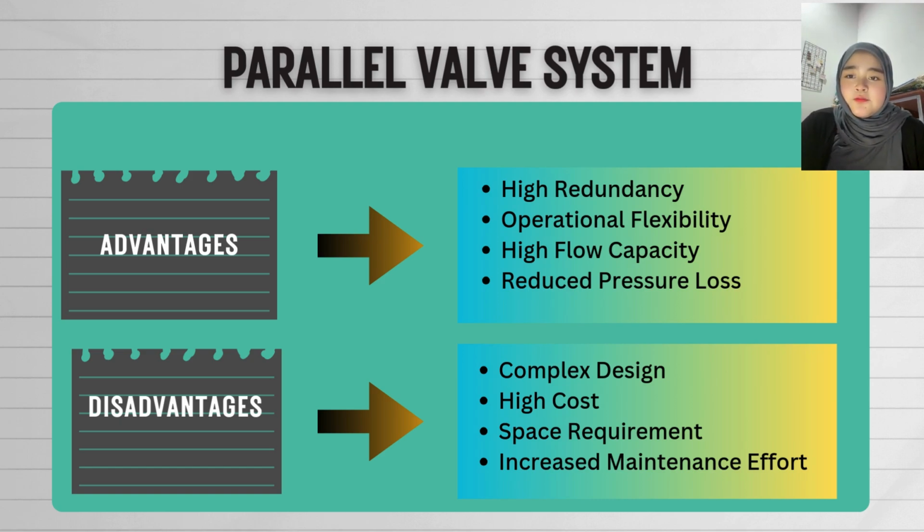And then lastly, for the advantage in a parallel valve system is reduced pressure loss. The flow is distributed over multiple paths, so the resistance in each path is reduced. So it results in lower pressure loss.